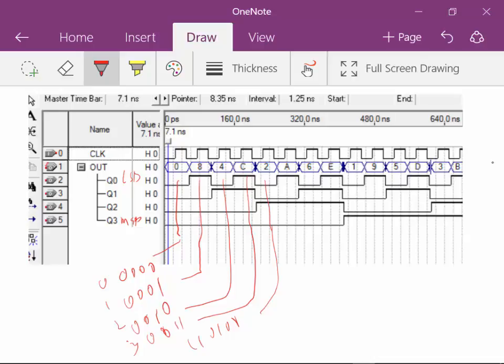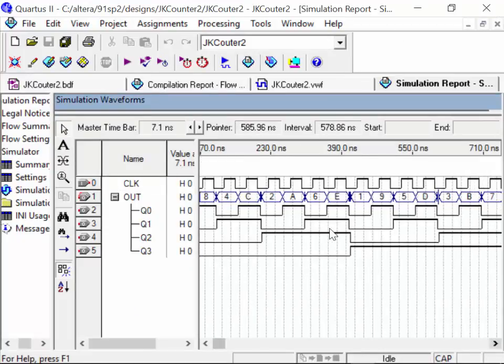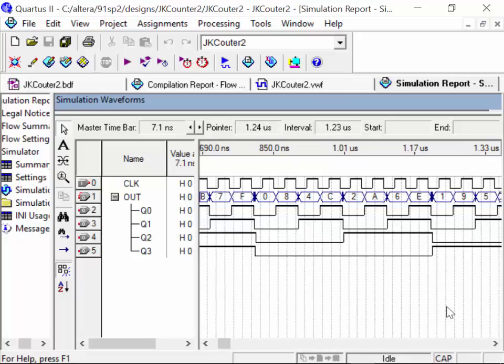It's doing what it's supposed to do, despite the fact that I got the bit order wrong. Because if we carry this on to the next page, we can see that we go to all ones here. We're all F here, and then our next one is 0. It resets back completely. So now we can do a very easy up-down asynchronous counter with just 4 flip-flops. Very straightforward, very simple.